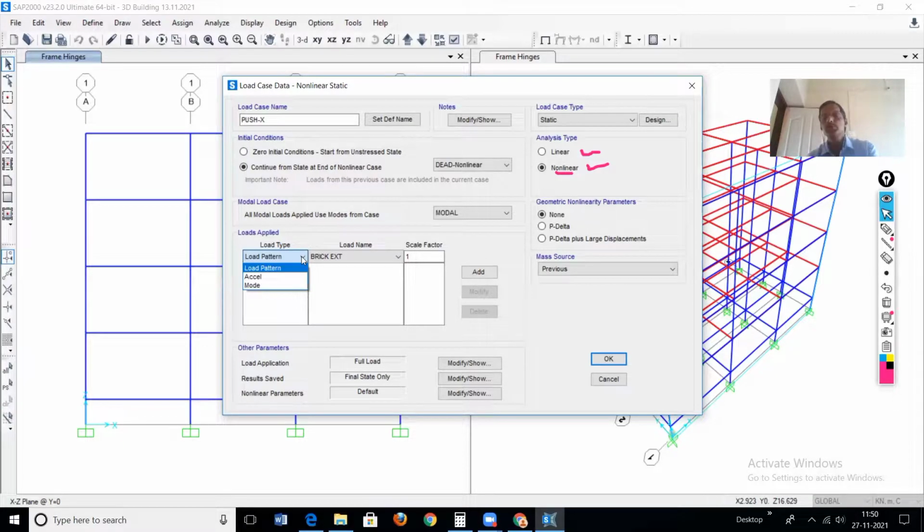So in this progressive failure of the structure, we come to know from the pushover analysis which is the weakest element. So that also we can identify from the pushover analysis. Therefore, pushover analysis is a very simple type of analysis, and from that we can identify which element needs to be retrofitted, that is, strengthened. For existing buildings, for strengthening purposes, this particular method is very, very useful.